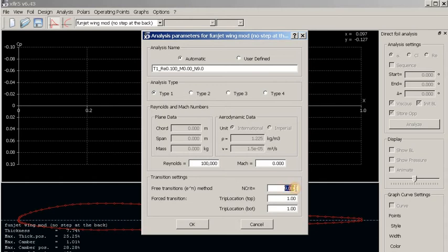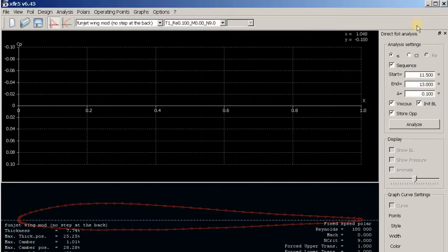Those two are important for slow flying airplanes. And as we have seen from the previous video, to fit the data from the wind tunnel, you might need to increase this number to 11, maybe higher. So this has to be kept in mind, that this number might be modified. And once again, those numbers are actually inside of the name of the file which is created for this simulation. So we press OK, and now this window.